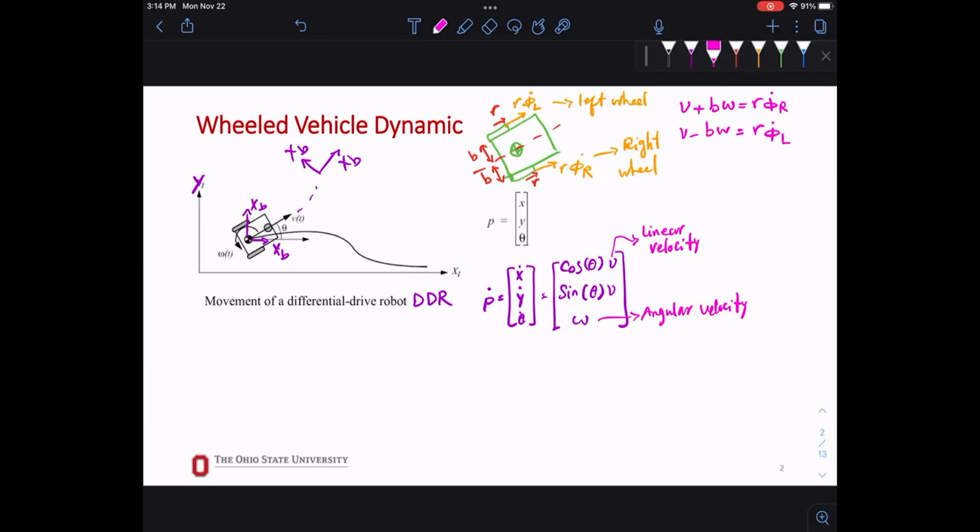So one of the wheels has to rotate in the opposite direction of the other one. Now, if both of your velocities in opposite directions are equal, what's going to happen? Rotate in place, right? To turn right or left, what should happen? One of the velocities should be less than the other one, right? So the path that the wheel with a higher velocity takes is longer in the same time. So that's how the turn happens.